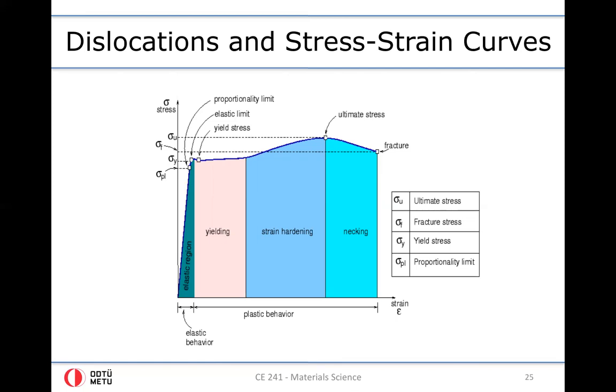You generally observe a combination of all these mechanisms. The macroscopically measured stress will be your force divided by the cross-sectional area, and the macroscopically measured strain will be your horizontal axis. The combination of the stresses within all the grains will be your macroscopically measured stress.